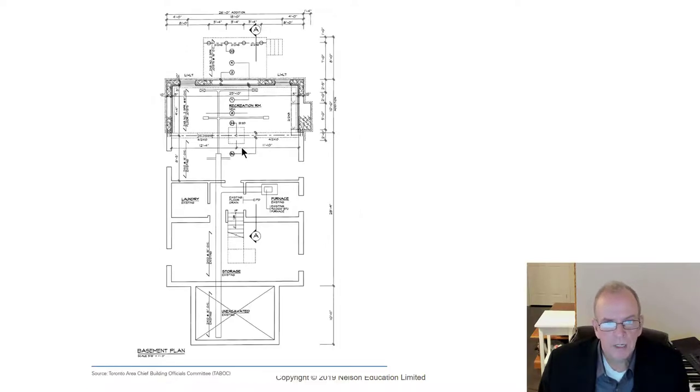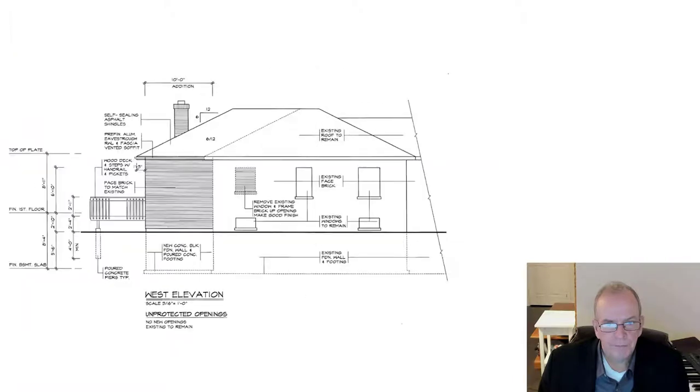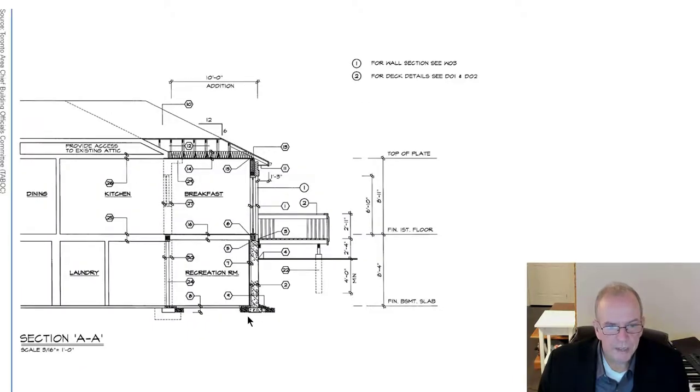So when you look at a section plan, it says 8'4" from the finished basement slab to the finished first floor. I'm not even worrying about this. I'm worrying about lining up the basement floor, and I'm worried about lining up the first floor. If it lines up at 8'3" or at 8'5", whatever it is, it's got to be at that to match up to that floor. So this gives you an idea, but this isn't rock solid the way it is in new construction. I've got to line up with what's existing.